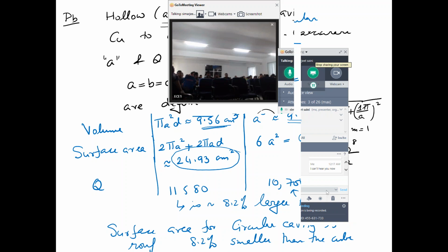And in the photonics area, the next question you probably would have asked is, okay, we went from a cube to a cylinder. A cylinder has a lower surface area, so the Q increases. Why don't we go to a sphere? A sphere has the lowest surface area possible for the same volume. The sphere should even give you better Q. Well, we don't go to a sphere in metallic structures because it's difficult to make a metallic sphere. It's difficult to polish a metallic sphere, and then it will be difficult to excite it too.